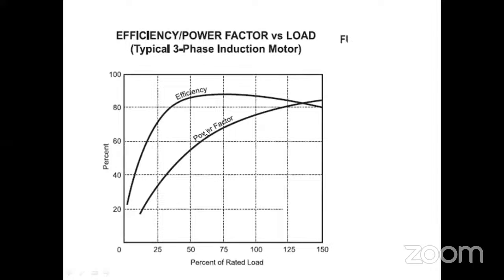In this curve, maximum efficiency occurs at 50% of the load because there will be a compromise between I square R loss plus iron and friction losses. All these things will come together and give us a curve where we may not get the maximum efficiency at full load.